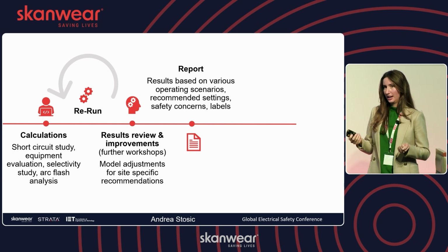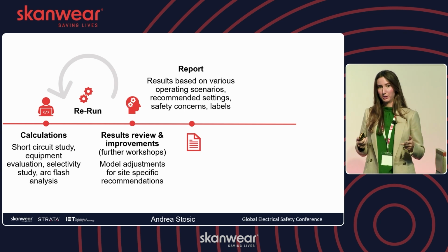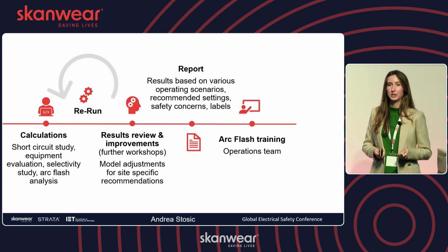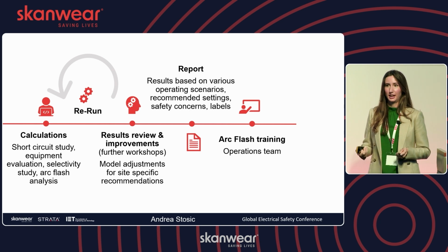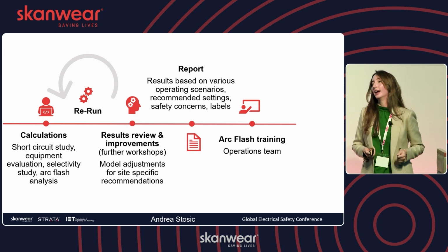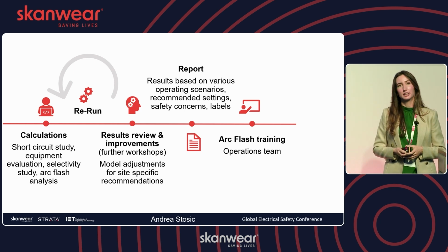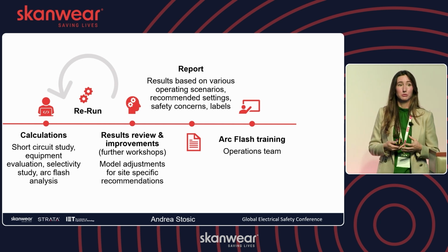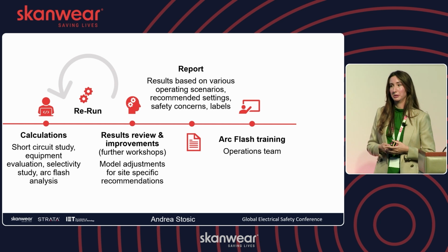So now that we have the report, the labels, the model, what do we do next? We train our site operations team. This is the team that goes and does electrical switching on a daily basis, perhaps, and it's critical that they understand the hazard because they are the ones exposed to the hazard. It's critical that they know how to read the labels and that they understand the importance of wearing appropriate PPE levels.